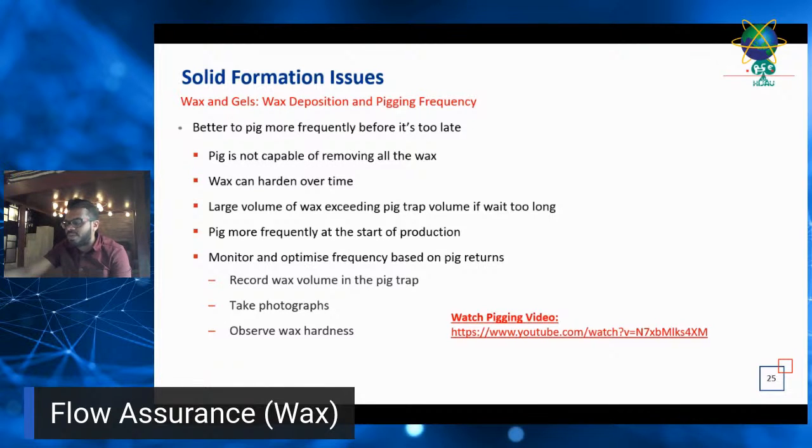Therefore, we need to optimize the pigging frequency using PipeSim or Olga simulation, as we need to not just look at wax, we also need to look at liquid management to determine the pigging frequency. I will show you a case study later on, of how we optimize the pigging frequency for wax and also for liquid buildup, for liquid management.